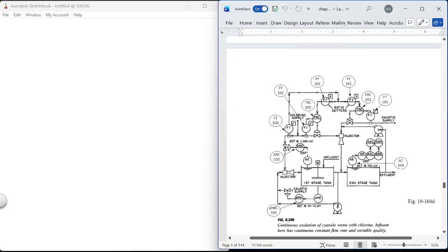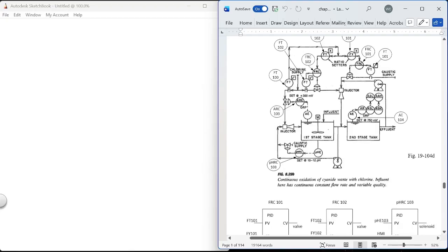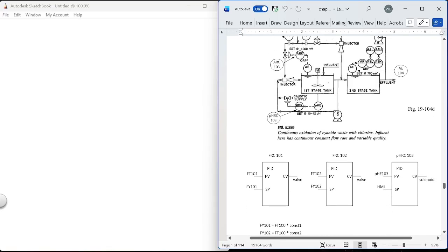And if you remember from the other night, we wanted to look at a series of, like, a P&ID drawing and find where the PID blocks were. And anytime you had a C as a third character, that tipped you off that it was a PID block. Okay, so that's the main important thing for you to be able to translate.